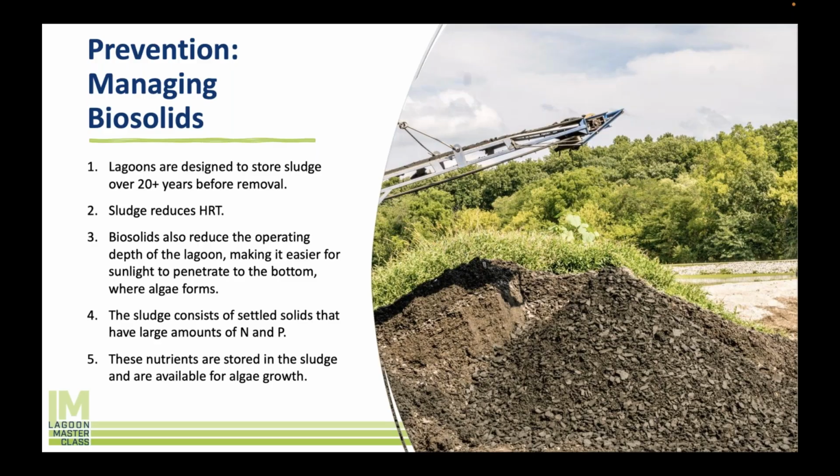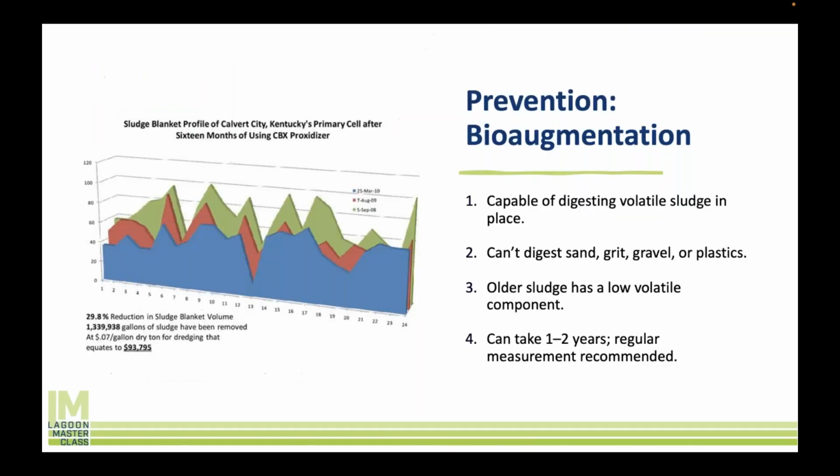And so one of the biggest things I recommend in general for lagoons, because sludge is an Achilles heel for lagoon systems in my opinion, is to have a good understanding of how much sludge you've got in your lagoon and start to actively manage it if you need to, and mitigate it in some way. I did a whole webinar on biosolids, two webinars on biosolids. I really encourage you to go back and watch those, because they talk in a lot more detail about how to measure it, what problems it causes, how to remove it if you want to remove it, etc. But I'll touch on a few things here.